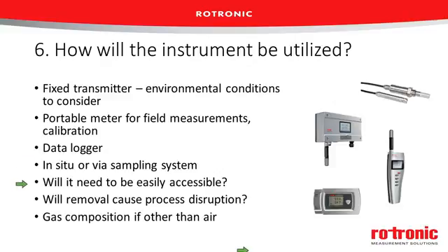Will you need to be able to access this instrument on a regular basis? That will determine, for example, if you'll need the probe on the end of a cable that goes to the transmitter, or it could also help you determine if you'll need a portable meter instead of a fixed meter.